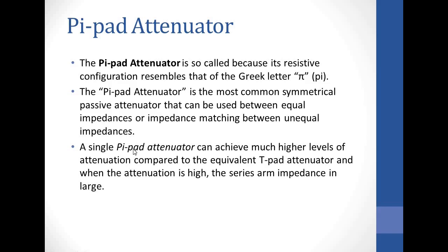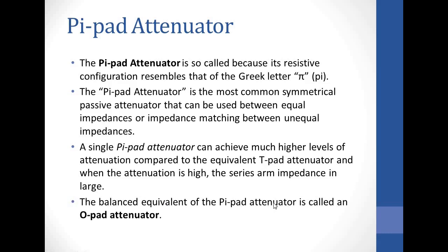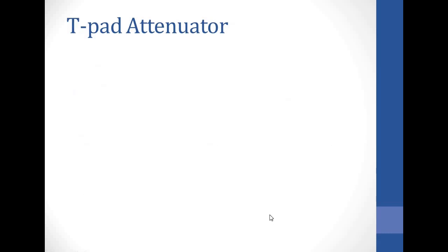A single pi-pad attenuator can achieve much higher levels of attenuation compared to the equivalent T. Alright. The balanced version is called the O-pad, like we mentioned.